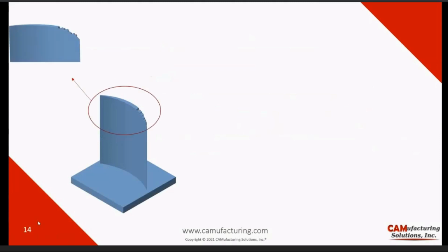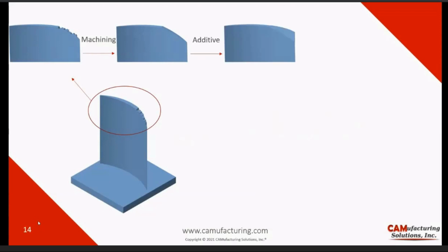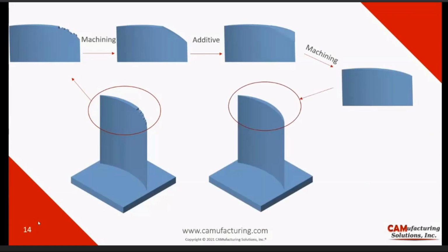In order to fix it, we need to have a closer look at the broken edge. If you have a broken edge like that, the first step to fix it by hybrid manufacturing is to machine the broken edge, getting a smooth surface in order to deposit material. The next stage is the additive part, where we build the broken edge again using DED, directed energy deposition. While doing hybrid manufacturing, we will always add a lot more material in order to do a surface finish and get a smoother finish, which is the last step. And finally, you will have your blade fixed.